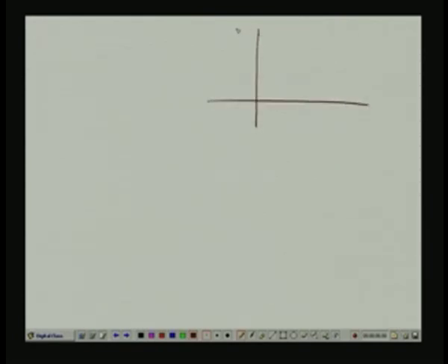Now, to explain that, what we do first, we just take a very simple case of single coefficient, say epsilon square, say W, only one coefficient. You can easily generalize this treatment to multi coefficient case, there is not much loss in terms of generality. Now, we know epsilon square is a quadratic function of the filter taps. Here we have got only one tap, that is W. So, epsilon square will be a quadratic function. Any quadratic function has got only one minima or maxima, in our case minima, because we know that there will be a minimum mean square error only.